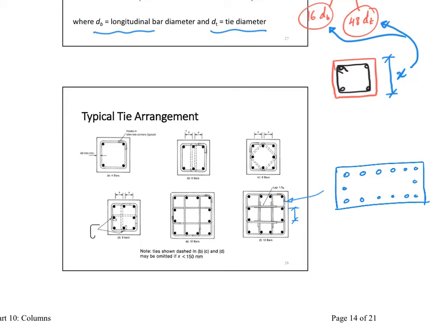Now, think about this. If I'm starting to put those bars, here is one. Here is another one. Right? I'm missing something. Regardless of the distances, once I see this shape, I will say, since you have two consecutive bars that are not being held by rectilinear ties, there's something wrong.